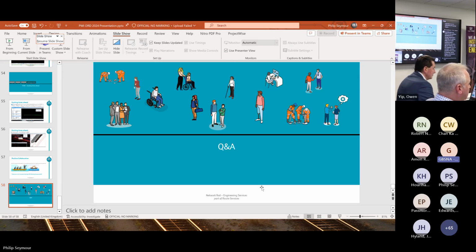Yeah, go. Another one. Final one from Alex. Can the slew display be moved, offset to the center line to ease reading? Can this be amended when editing feature definitions? Slews, that's just a view display. I think we can. Yeah, I made those bigger. It could be smaller. I actually enhanced them just for the screen to make them bigger numbers. I think we can shift. I'm not sure about the shift, but we can turn stuff on and off. So you may just want point number, you may just want the slew, you may want instantaneous radius. There's other things you can do, existing cant in there if you want as well, design cant. But I think we can shift slightly.